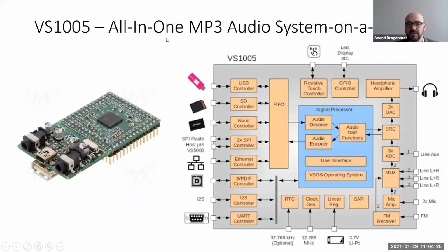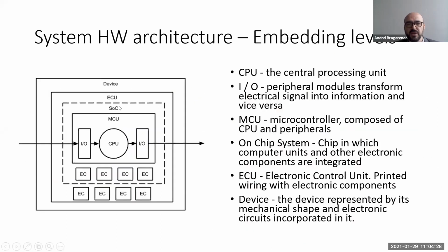Going through, we have the microcontroller now. Next level, system on a chip. Let's say, what is a system on a chip? If a microcontroller is a CPU that has some generic peripheral modules embedded inside, a system on chip is a microcontroller that already has some IO, yes, but also has other specific controllers. A very good example of such a device is the phone. If you open it, you'll see that you have a PCB and only one big chip.